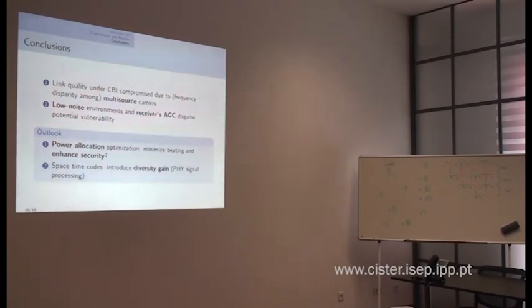And then there is another way, which in fact has already been tried, and this is a very common practice in wireless networks, which is that you use something called space-time codes. That will pre-code the signal before you transmit it, in such a way that the amplitudes will not be the same, even though they contain the same information. I'm not going into detail because this is a complex topic, but if you do that, then you require going into the physical layer of the protocol stack and doing modifications. So that is a problem for low power wireless networks because typically you don't have access to that because they're very simple radios. This is built up in silicon. And traditionally, for the past 10, 15 years, no one has had access to that.